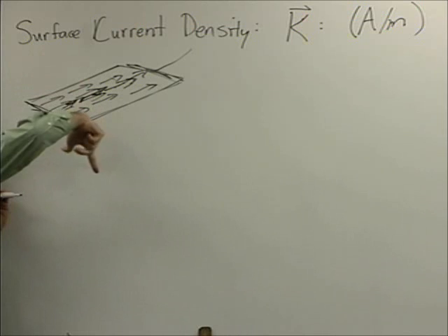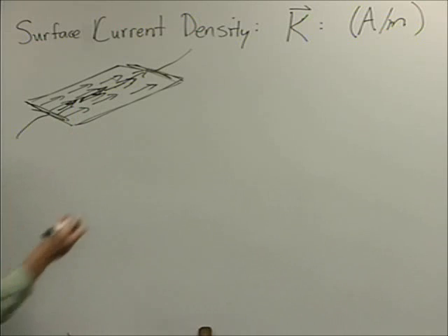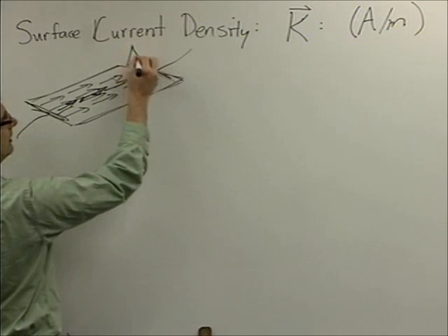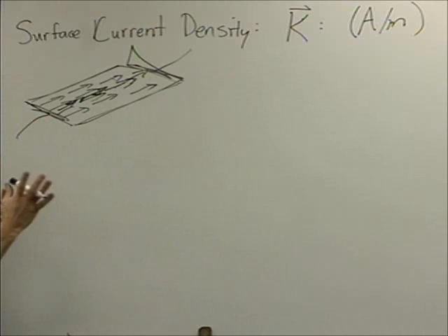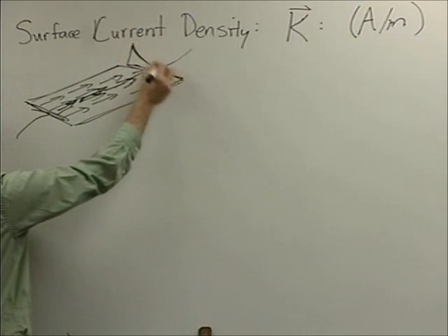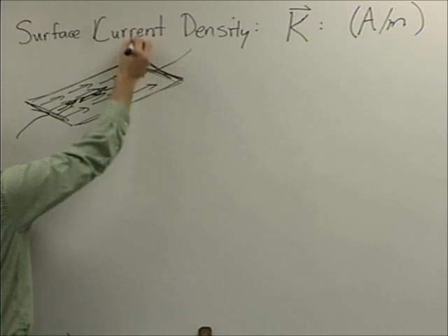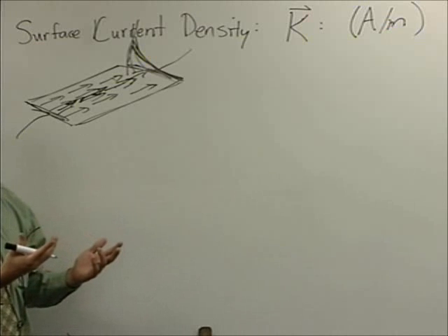Crossed with the field, there's always a force pushing them to the right. If the B flips, then it's always a force pushing them to the left. And the Hall effect is some guy named Hall that basically found out that for these sheets of metal, the K, the current density, gets pushed to one side, kind of an exponential looking decay, and that exponent becomes steeper and steeper depending on the strength of the magnetic field.